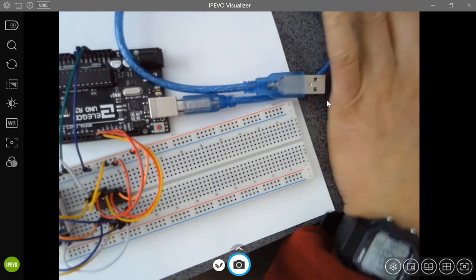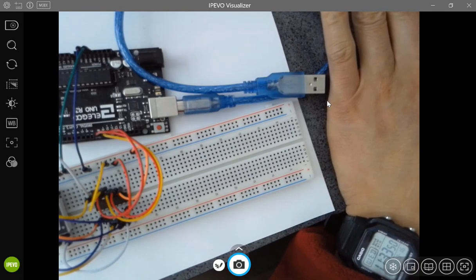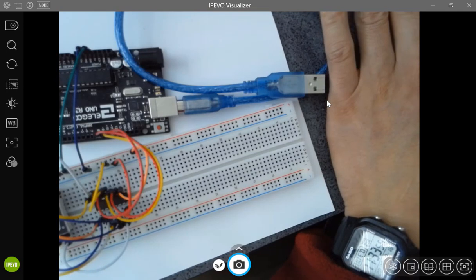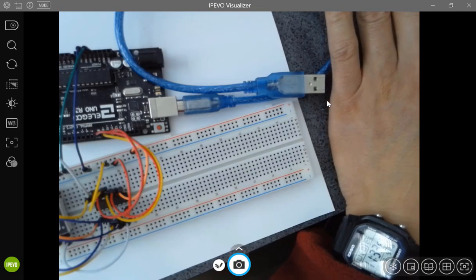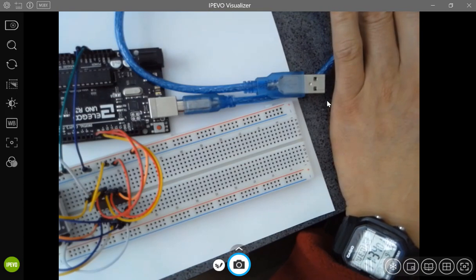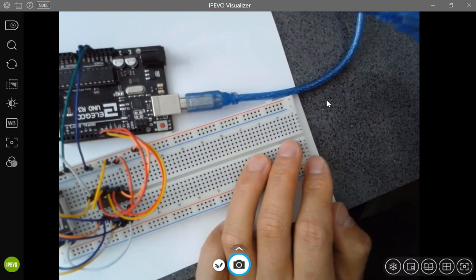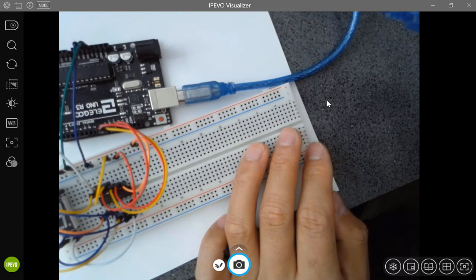I didn't plug my laptop in anywhere, right? So you know I have a battery in my laptop. The battery is normally 12 to 20 volts, let's say 20 volts. So there must be a voltage regulator inside to step down that voltage to 5 volts to supply the digital chips and the USB. That's where the 5 volts comes from, okay?